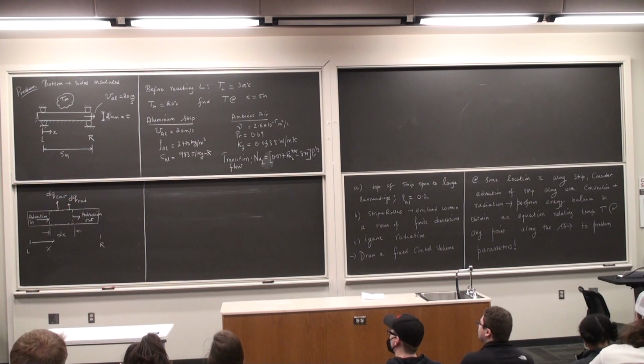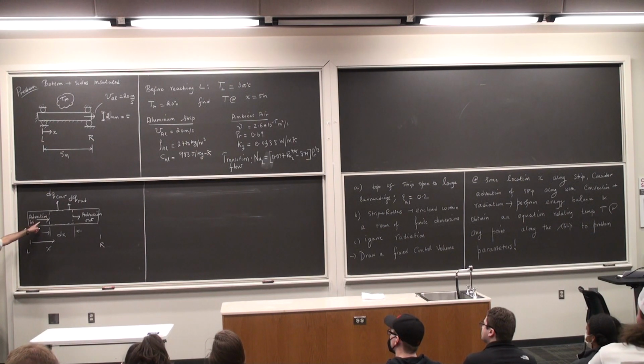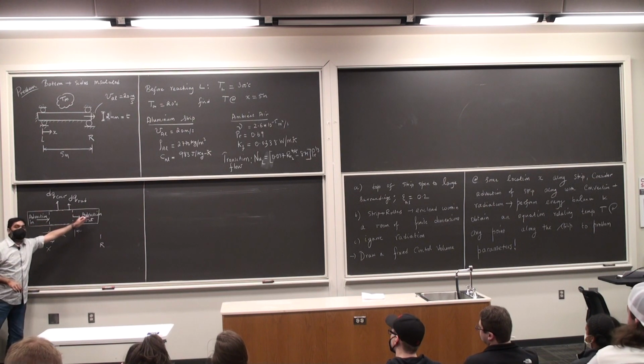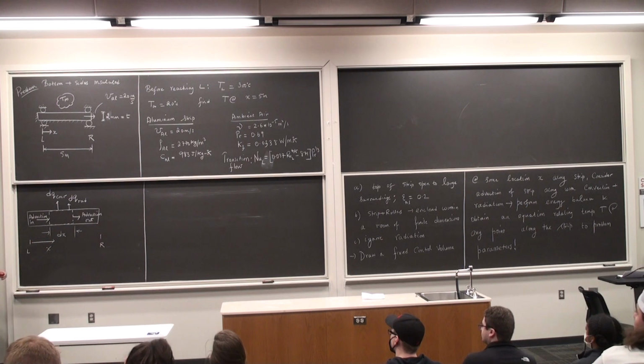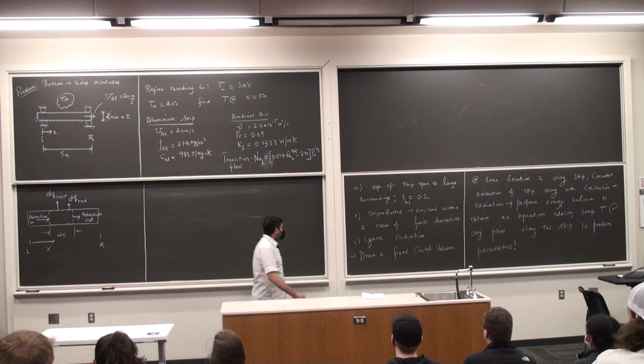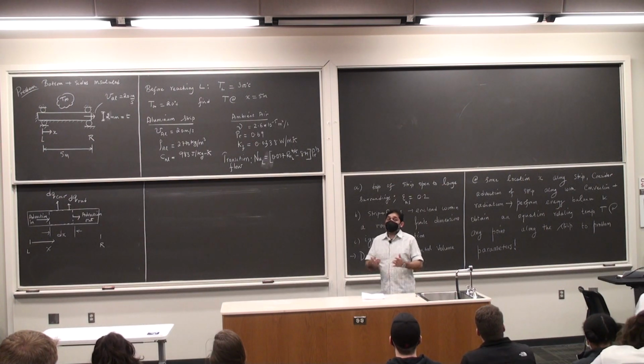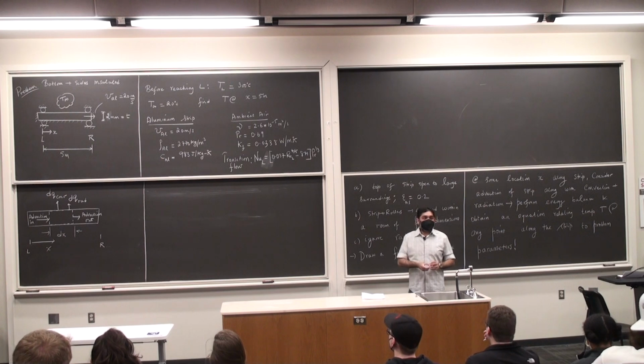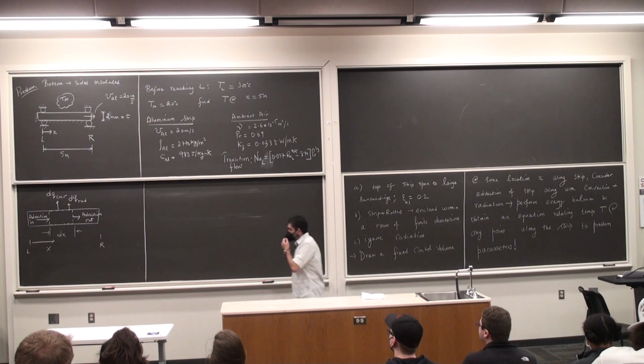Does this make sense to everybody? There is energy flow coming in, which is taken care of by the fact that the strip has a certain mass flow rate, so this is entering in. The strip is going to leave the control volume after a certain point in time, and as it passes through the control volume, there is energy transfer due to convection and due to radiation. Okay? So these are all the quantities that are involved, and now let us write everything down. If you have this, you're pretty much done with the problem. The rest is just details, which anybody can do.